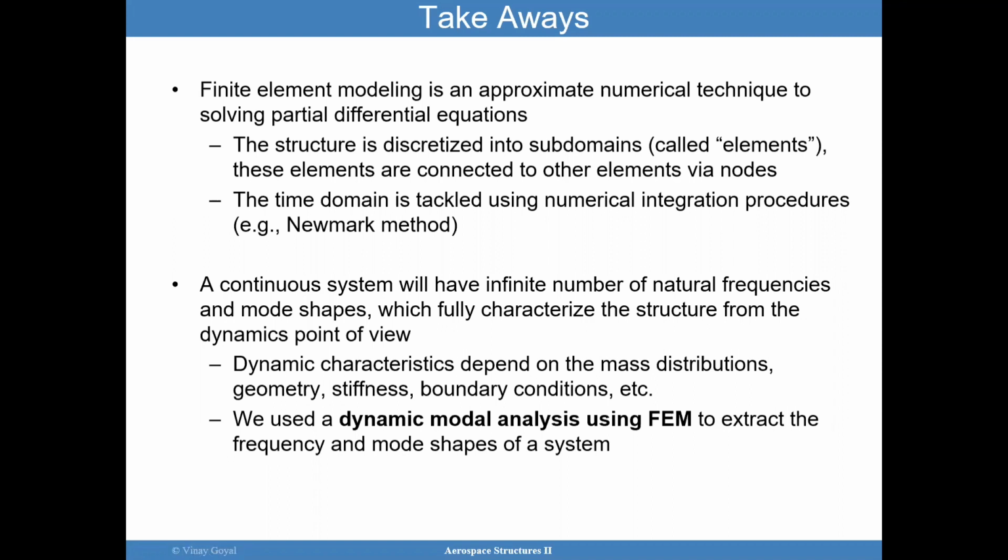Finite element modeling is really an approximate, numerical way of solving partial differential equations, where we're trying to solve for variables of interest such as deflections. These deflections need to be solved not only over the spatial domain, but also as a function of time. To accomplish this, we have taken the structure and discretized it into subdomains.